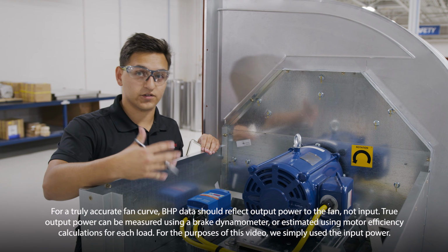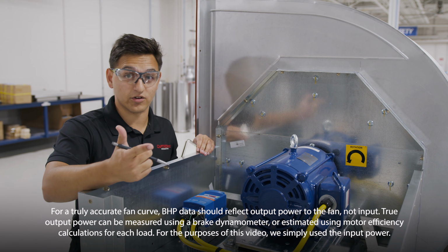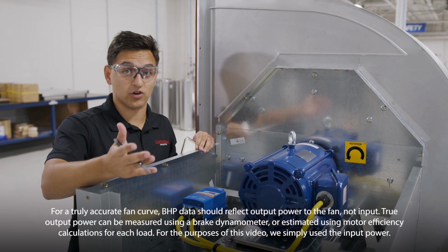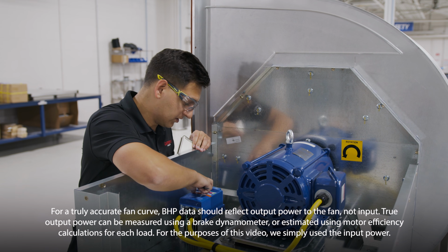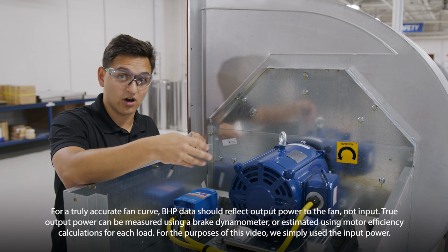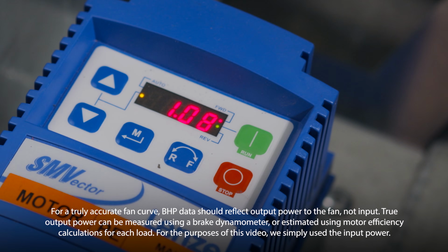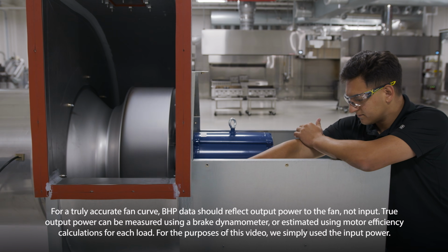So at each point, we need our CFM, our static pressure, and our brake horsepower. So we've covered CFM, we've covered static pressure. Now we need the brake horsepower at each point during our test. We can grab that from our VFD. So during our test, we can come to a certain parameter on our VFD, in this case P510. So take that reading, combine that with our CFM and static pressure, and there we have all of our data for 1 point during our test.